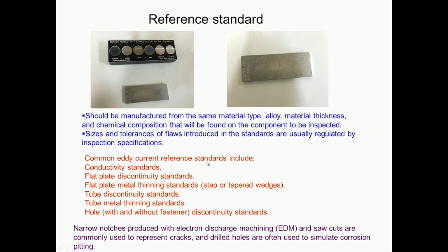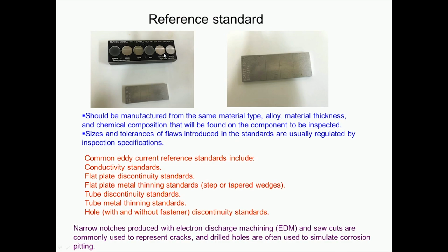And these are the commonly used eddy current reference standards which includes conductivity standard which is this one. So, these blocks are of known conductivity and they have different conductivity. So, using these blocks of different conductivities, you would be able to calibrate the instrument for the electrical conductivity. Then you have flat plate discontinuity standards and one of them we have seen in the video, which is this one.